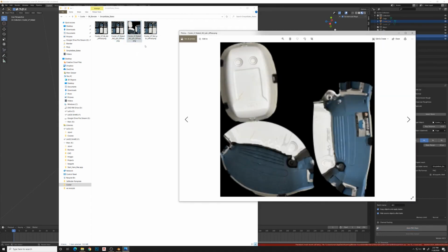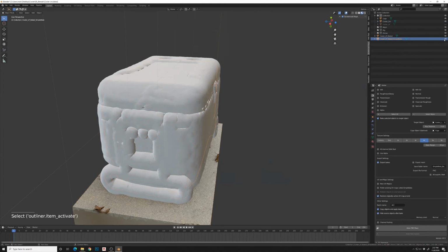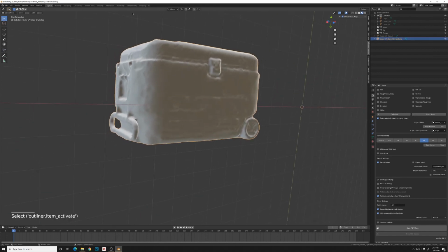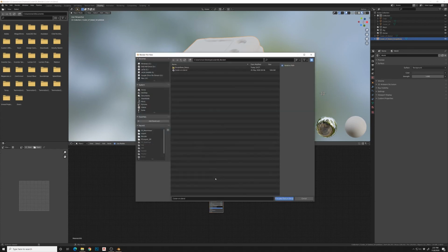All right, so here's our 4K3. You can see it's a lot less maps going on here. I've got a new model. I'm going to turn this off. So we've got a new baked model here. I'm going to go into shading, select this guy, and make a new material. And I'll do Control Shift T and use the node wrangler. Go to wherever it is, Blender, Simple Bakes, and we did this 3 here.